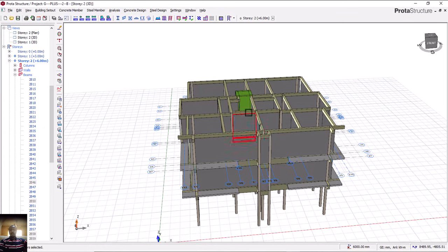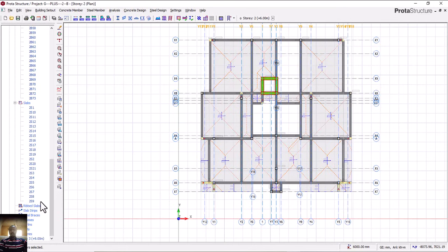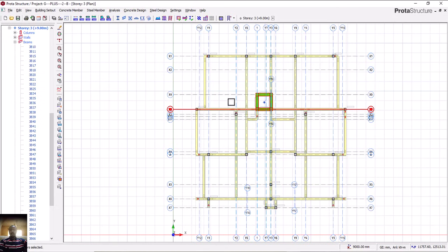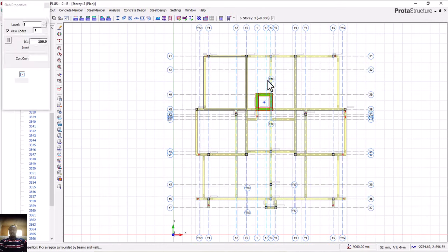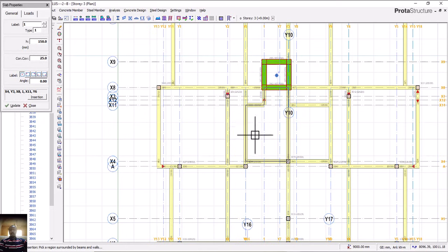Let's now talk about where we are having a water tank. So come back to this place now. Around this place we're having a slab. I'll come here now, property, I have a slab. Since it's a water tank around this place, I'm going to be using a thickness of 175 minimum, and see if it will pass.